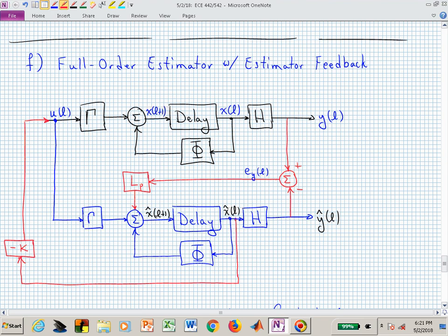That's a head scratcher. So what do we want to do? We're trying to do two things. We're trying to estimate the state X with X hat, and we want to use that estimate, X hat, to control the system. So there's two sets of dynamics. The estimator dynamics and the system dynamics, or the behavior of the system. Which do you think needs to be faster in quotes?